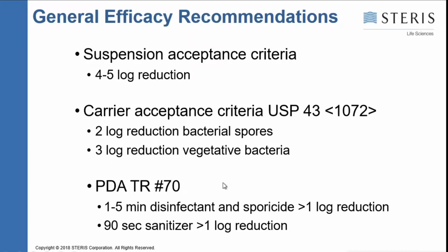And then we do have the PDA's Technical Report number 70. In that, we recommend a 1 to 5 minute wet contact time with disinfectants and sporicides and obtaining a greater than 1 log reduction. And with sanitizers like IPA or ethanol, going after a 1 log reduction in 90 seconds.